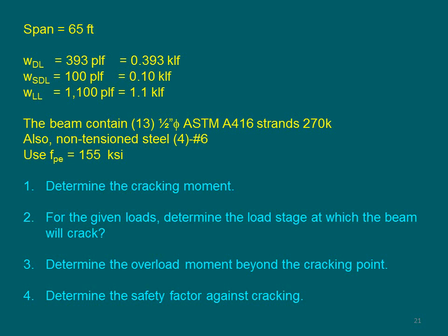Therefore, I'm going to say the overload moment beyond the cracking is going to be very limited. Why? Because I applied most of the loads that I have for the service, including dead load, superimposed dead load, and most of the live load, and then I start to see some cracking. So the amount of overload beyond the cracking point is going to be very small. This gives me an indication of how much cracking beyond that point is expected.